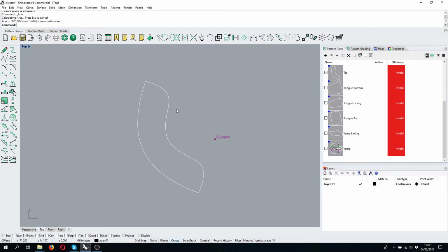Okay, so these are some of the basic utilities that I can use for measuring properties within my model. So I can measure linear distance, I can measure distance on curves, and I can measure areas. Another thing that I can also see from here is the direction of a curve. This is also quite a useful tool, and this allows me to see what is the direction and the flow of this curve and where the point of connection of the curve in this case is.